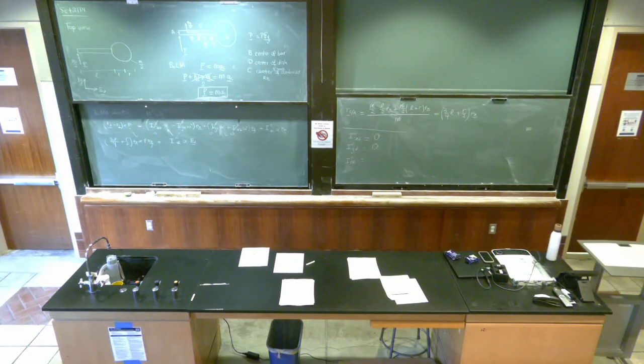For this type of problem, there's no IXZ and IYZ. It's not because of displacement; when you're integrating xz to calculate ICXZ, x equals 0 is a plane of symmetry. For every point with coordinate x and z, you have another point with coordinate x and minus z. Or you can use the parallel axis theorem to see that. AZ is going to be 0 for both, and about the center of mass they're also 0.